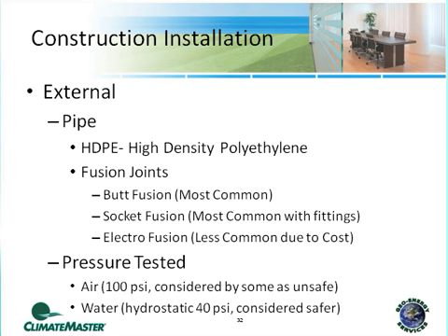Electrofusion has a tendency to be pretty expensive, so I've mostly seen it in situations where they're trying to do a quick change out in the field. Somebody accidentally cut the pipelines and they're out there digging a small trench trying to make a patch repair or something like that. Or in extreme cold temperatures where the heating irons just can't maintain temperature because the ambient air temperature is way too cold outside, so they may switch over to electrofusion joints instead.